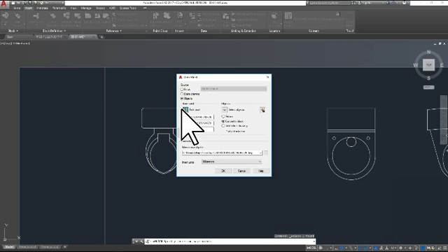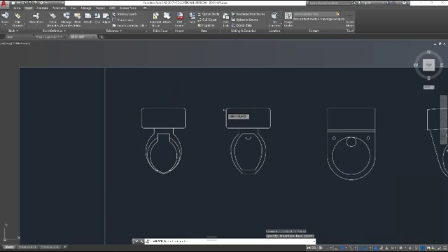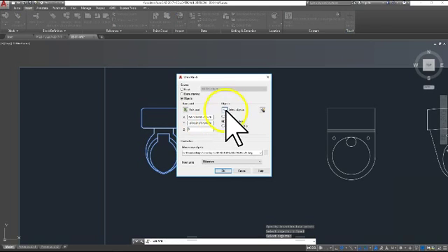Next, mouse to the Select Objects cell and click on the icon next to the words Select Object. Here, you simply click on the object and push the Enter key on your keyboard, which takes you back to the Write dialog box. Also, in the Select Objects cell, click the radial button next to the words Convert to Block.